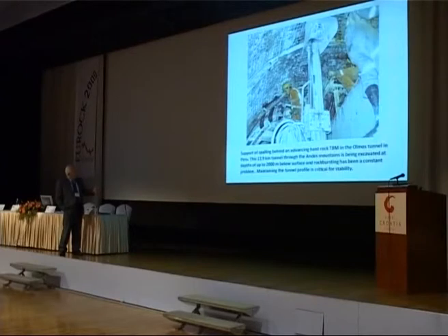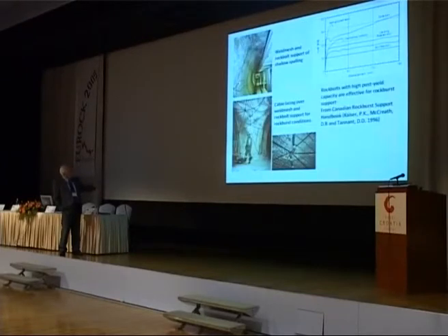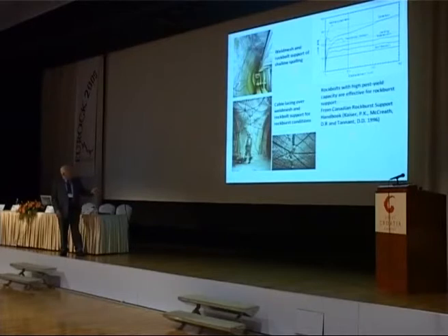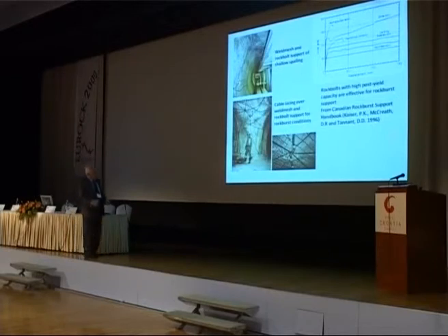This is a relatively small spall held by rock bolts and mesh. This is very high stress in Chile, where rock bursting is an issue and where a cable lacing has been used. So in addition to the mesh, you have these cables anchored on a very firmly embedded pin, and giving a lot of ductility and support to the rock.